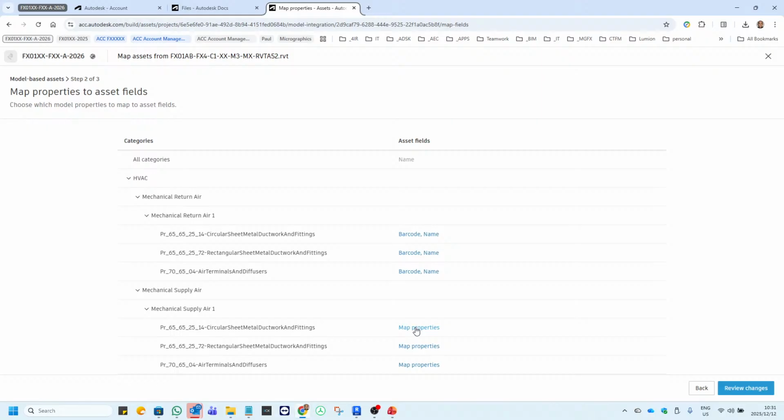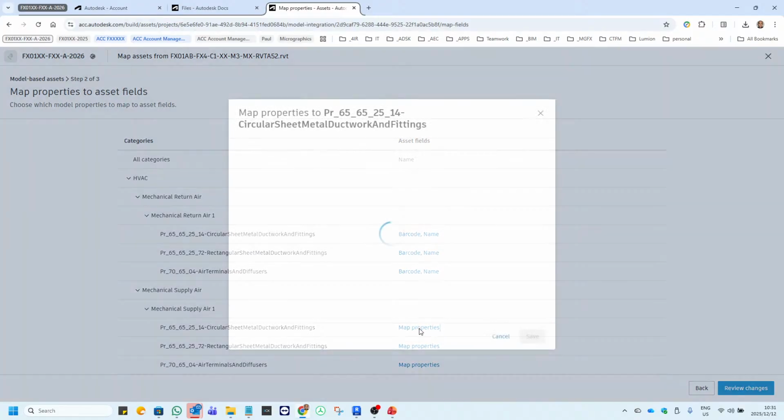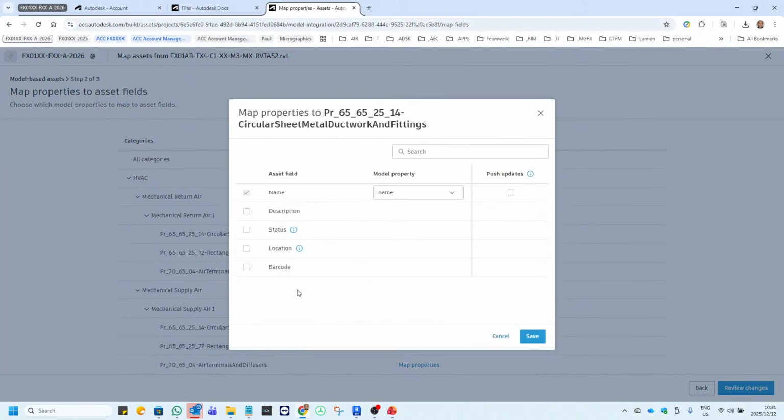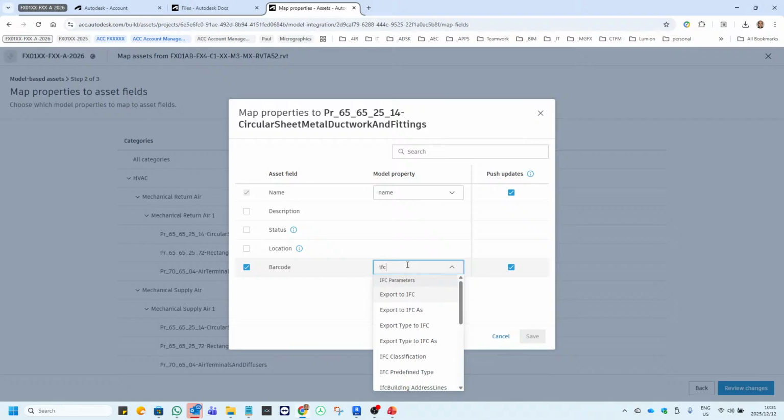And if you're dealing with most other files, IFC, Industry Foundation Classes, of course, is a common interchange of files between different BIM packages, just like DXF is to DWG, so IFC is to BIM. So you should find that that's quite common, and you should be able to take pretty much any software and export that to an IFC format, which means that it should also generate for you your IFC GUID. I'm going to map the names IFC GUID.